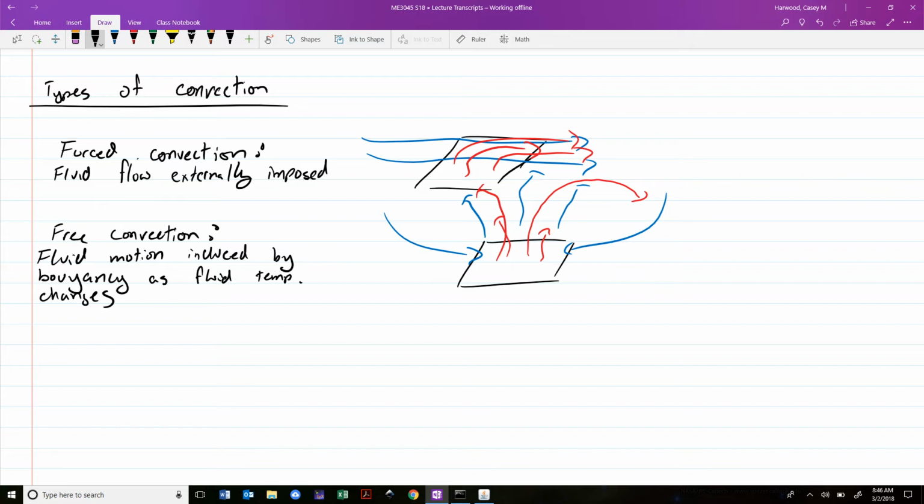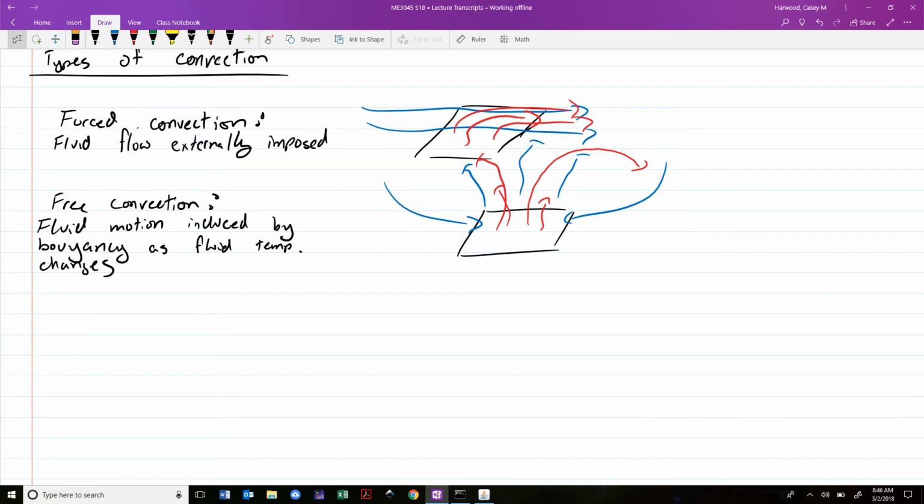So, the idea here, and what I want to take away from this, is that convective heat transfer is tied closely to the way that the fluid next to the object is moving. Right? The behavior of that fluid's velocity is going to tell us a lot about the way that heat transports into the fluid and again gets either pulled away or cycles out through this free convective process. And so this leads naturally to the idea of, and cue the groans, boundary layers.